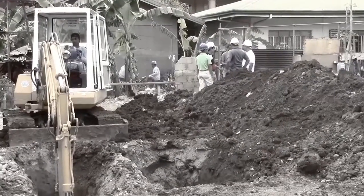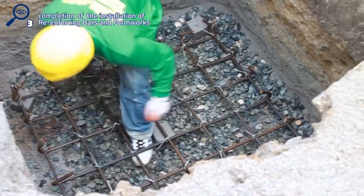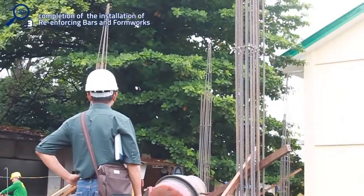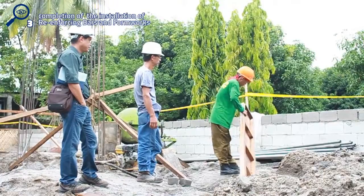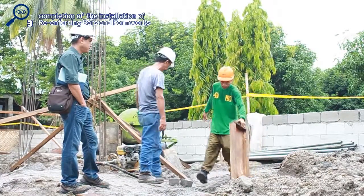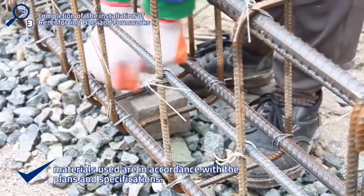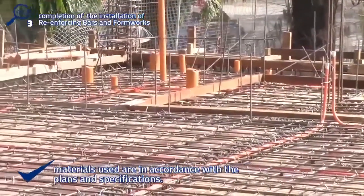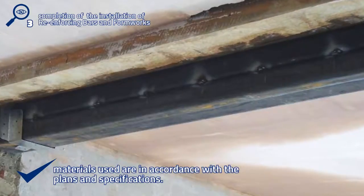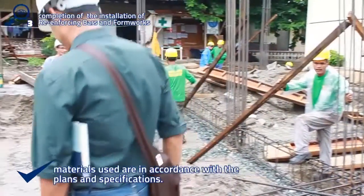Once the contractor has completed the installation of the reinforcing bars and formworks but prior to the concreting of footings and the installation of tie beams, the engineer should carry out key inspection point number 3. The engineer must check that the materials used, specifically the reinforcing bars for the footings, the tie beams, the columns, the floor beams, the roof beams, the suspended floor slabs, the ground floor slabs, and lintel beams are in accordance with specified grade as required in the plans and specifications.